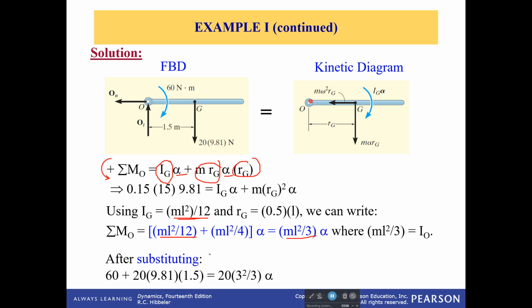And we add everything in there, what we have is, okay, all of this put together, this moment of inertia, everything else, is going to be equal to this equation, where this is from our sum of the moments equation, this is our applied moment, and this is the moment caused by the weight. So solving those, we get our angular acceleration is 5.9 radians per second squared, where it's always radians, and our tangential component, plugging this back into our previous equation, is going to be 19 newtons.